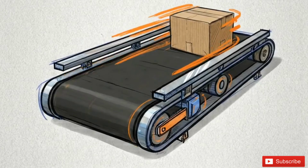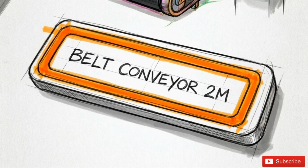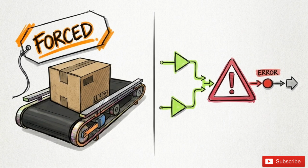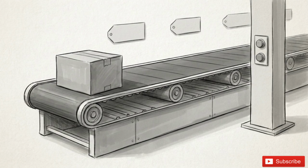Firmly. Now, before doing anything else, turn that tag back off. If you leave a component in the forced state, you create a manual override. Later, when you try to run your automated programming, it will completely fail because the manual force blocks the software logic. Manual testing is an important diagnostic step to prove the hardware actually works, but the environment must be strictly reset to 0 before we can start wiring the logic.